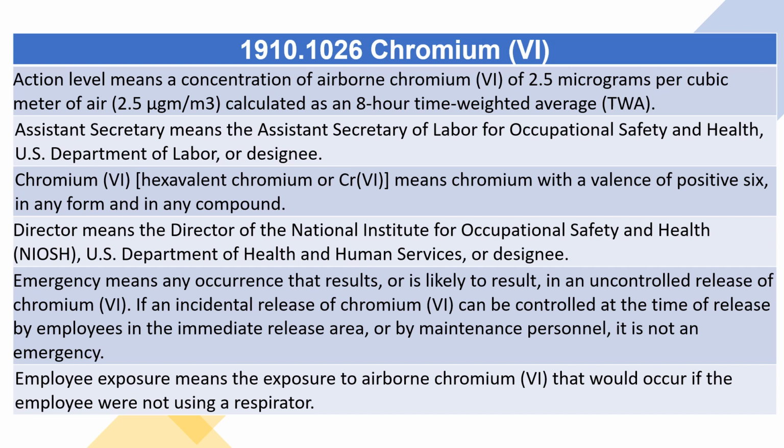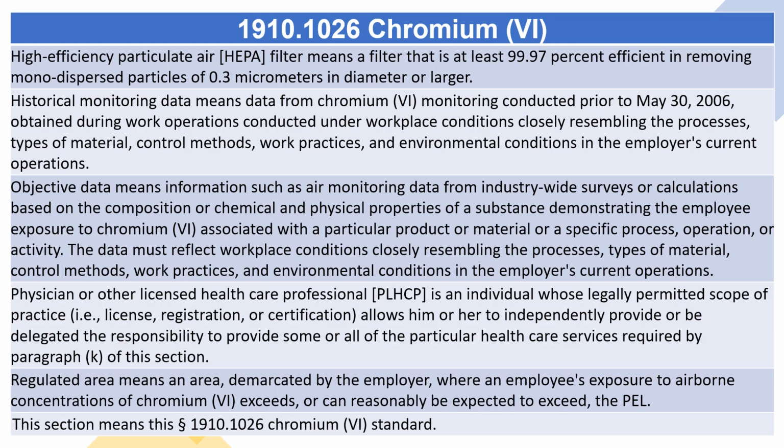Emergency means any occurrence that results, or is likely to result, in an uncontrolled release of chromium (VI). If an incidental release of chromium (VI) can be controlled at the time of release by employees in the immediate release area, or by maintenance personnel, it is not an emergency. Employee exposure means the exposure to airborne chromium (VI) that would occur if the employee were not using a respirator. High-efficiency particulate air (HEPA) filter means a filter that is at least 99.97% efficient in removing monodispersed particles of 0.3 micrometers in diameter or larger.